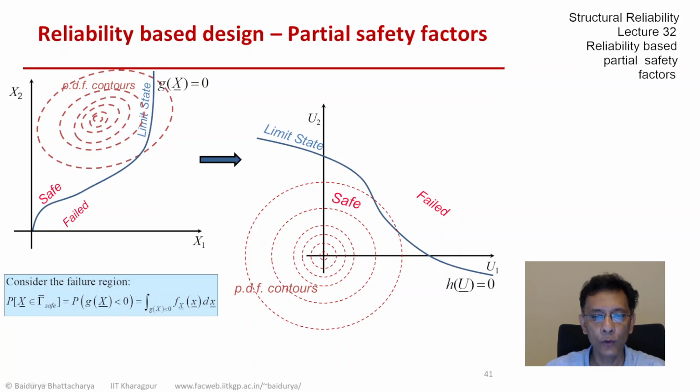After seeing how we can develop a design equation in terms of nominal quantities and a factor of safety in the two variable case, where the factor of safety is tied to a specified target reliability, provided we know the basic statistics like the mean, the coefficient of variation, the bias factors, and so on. Let us now move on to the more general n-dimensional case.